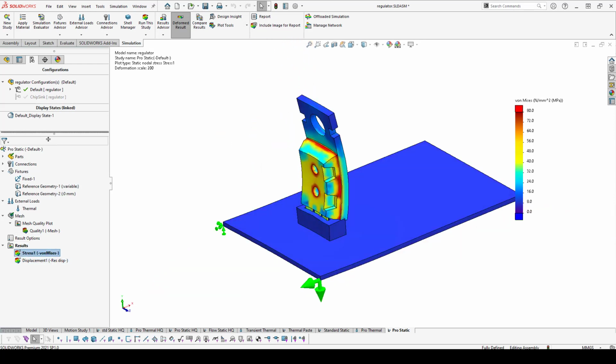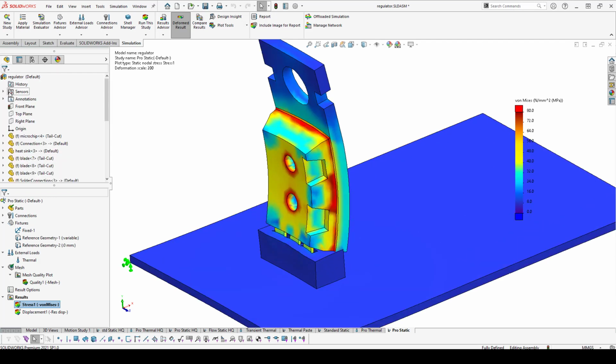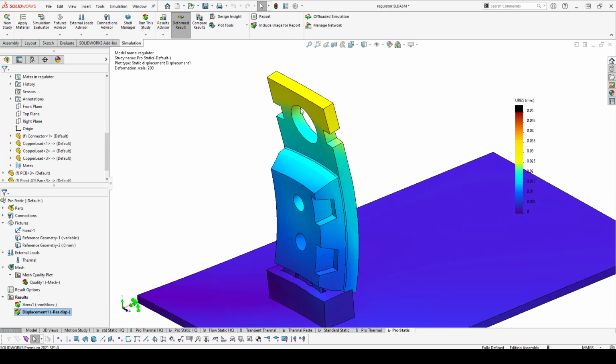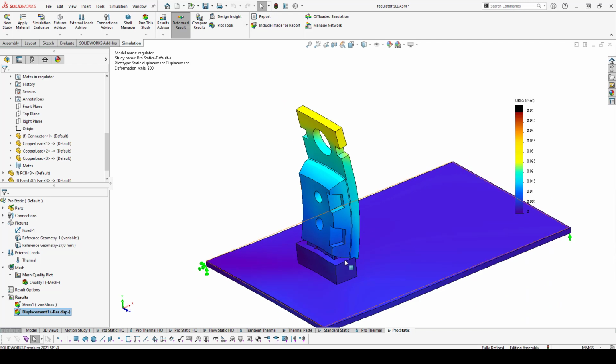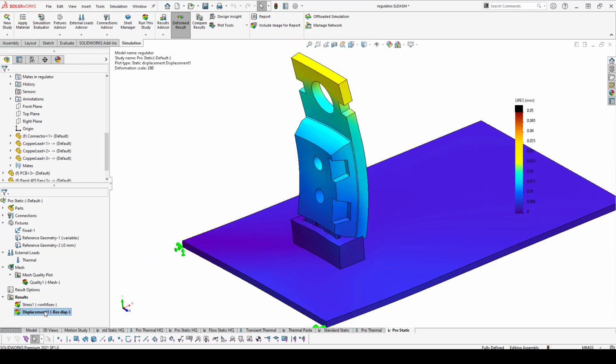First and foremost, the key result I was looking at. And they look pretty similar to what I think I saw before. If I go back up and look at that same sensor, now I'm getting stresses like 91.8. They're actually a little higher than before. And my displacements, you remember seeing some black up here, and I don't see that anymore. Okay, I have the same scale set here, so it displaced by less. Me including this extra stuff made it displace by less. That doesn't seem right, does it?